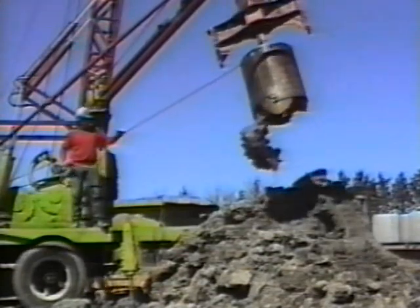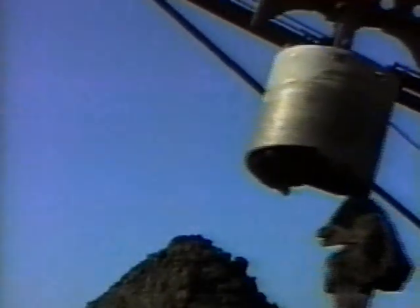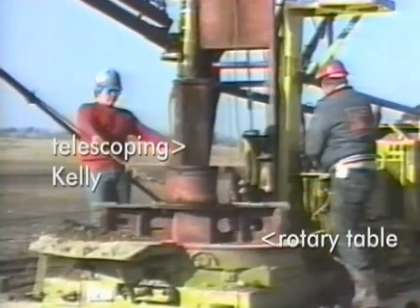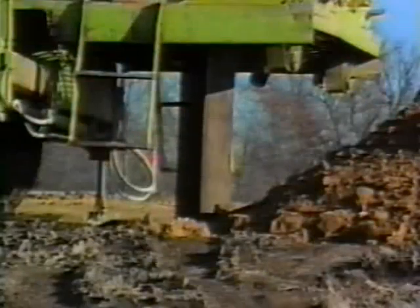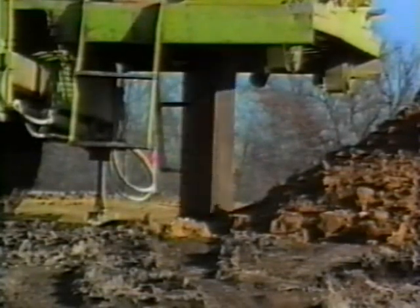Note that no flushing media is used, since the bucket auger removes the cuttings as hole penetration occurs. This produces cuttings which are clean, unmasked, and representative of the geology. This drill utilizes a large diameter table drive to rotate the telescoping Kelly, which in turn advances the bucket auger. Penetration rates are generally quite rapid in favorable conditions.